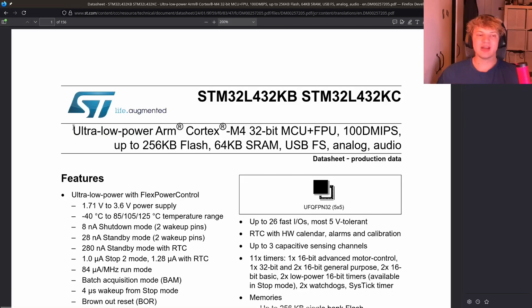This is also described as an ultra low power chip. This is important for us because of our small scope. We can add battery power as a power source later on down the line. And for that, we'll want to use an ultra low power chip maybe in advance so that that's an easy transition for us. Now, you'll notice that I didn't add battery power in the previous section. That's because I'm adding battery power in as a later design iteration we can do somewhere down the line after the first prototype. But I'm making this decision now knowing that that could be a possibility in the future, so we want to use a low power chip.